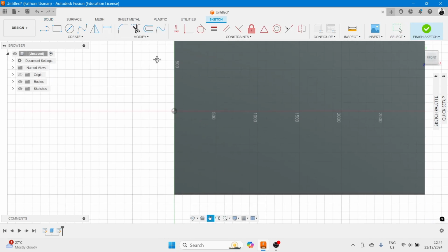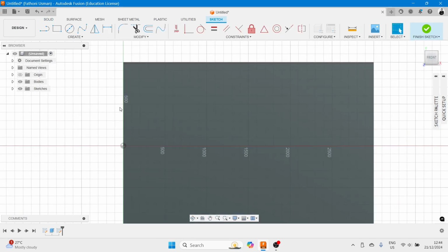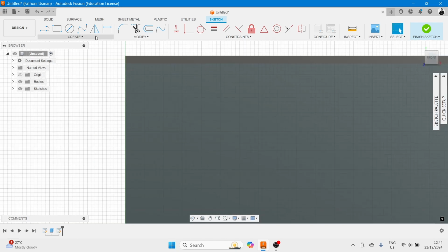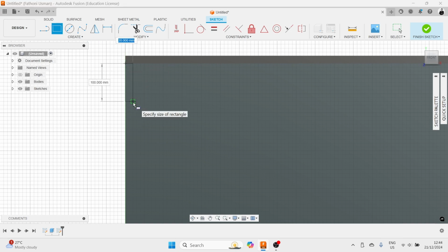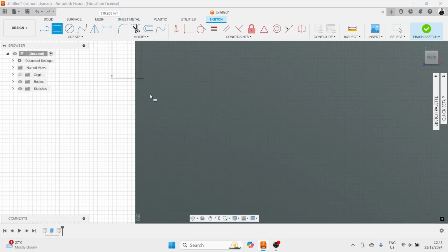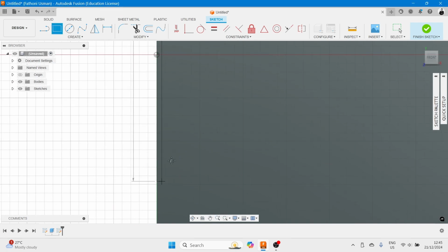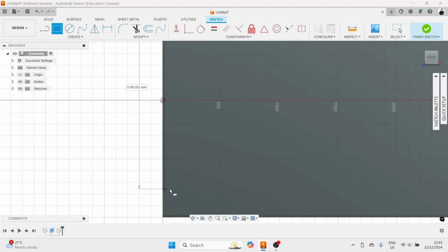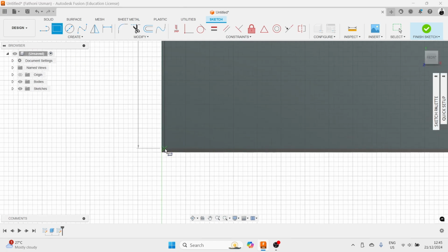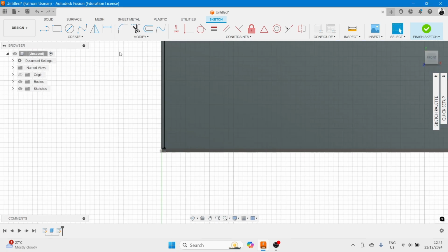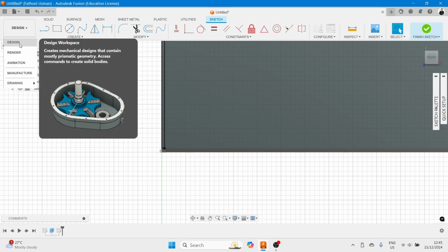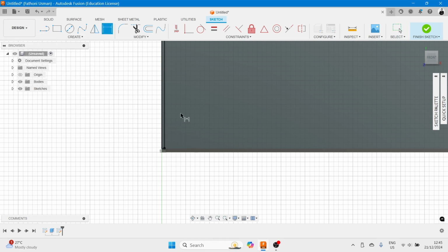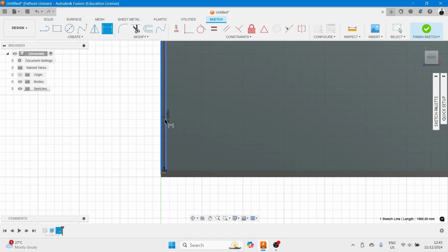Then after that you just simply create the stiffener using the point there, and then you can see that the thickness is 15 millimeter. And then after that, anyway, you can edit it later on here. If you want to check the design, create sketch dimension from this line to this line, 15.